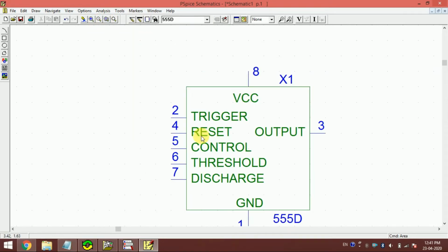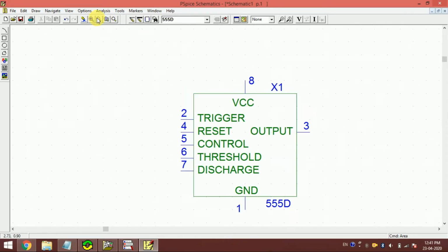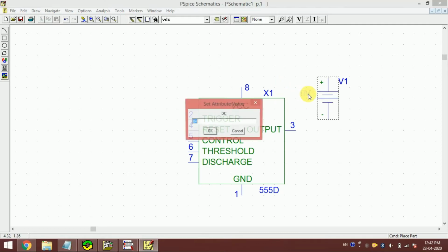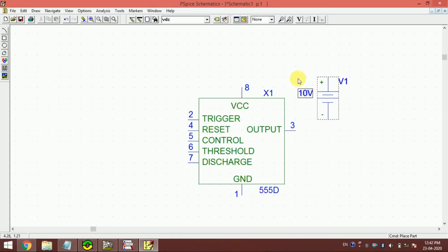this circuit generates a rectangular wave as output. So I am showing you what it does. But first, let me make the circuit. So we will need a VDC, which is the supply voltage, and we usually use 10 volt. You can also use 5 volt. Okay. So I connect this to pin number 8, which is VCC, and I use a ground. So we run the biasing.